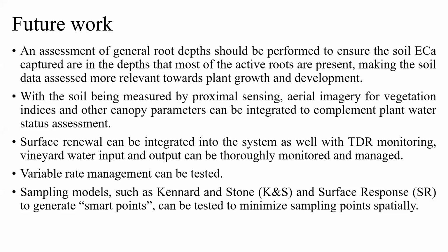And with the soil being measured by proximal sensing, aerial imagery for vegetation indices or other canopy parameters can be integrated to complement plant water status assessment. And surface renewal can be integrated into the system as well with the soil TDR monitoring. By doing that, the vineyard water input and output can be thoroughly monitored and managed.